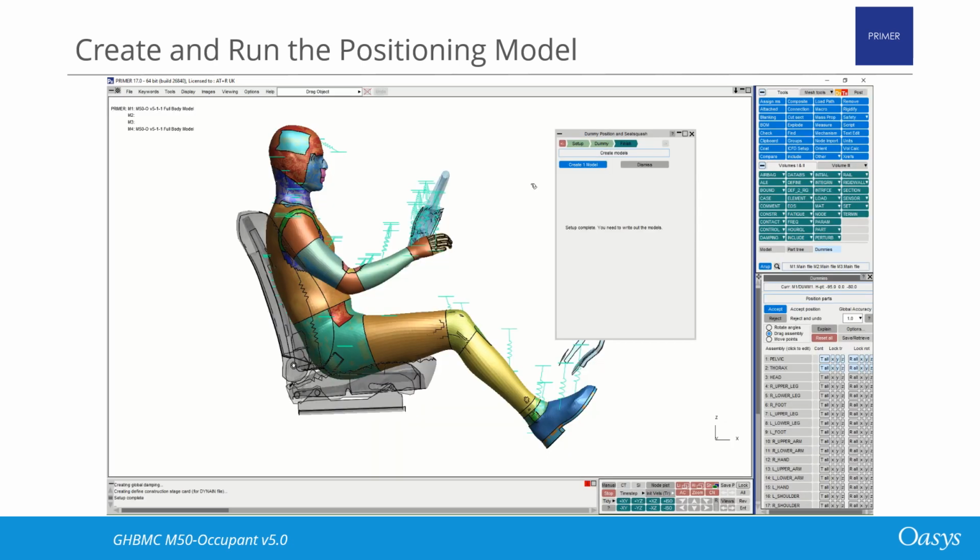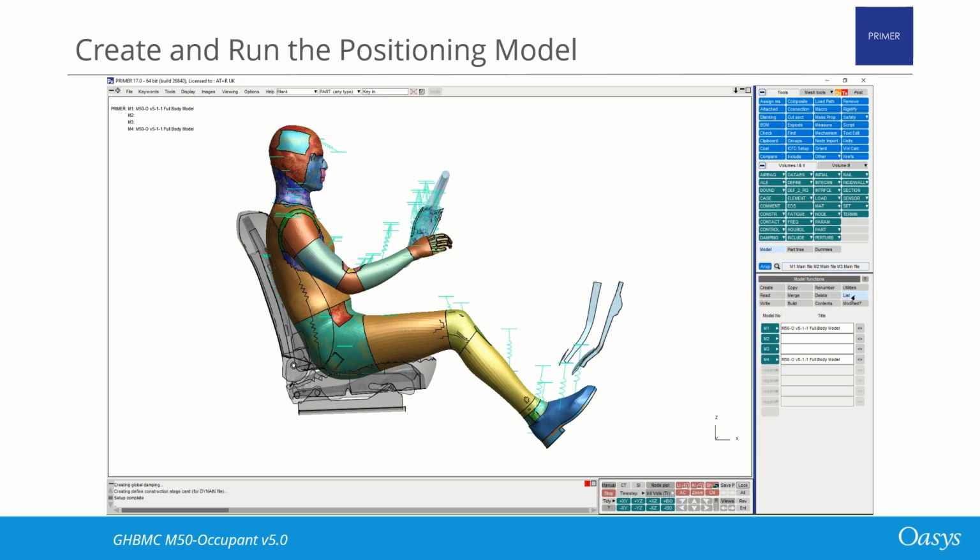So once complete, you can see that Primer has created a new model. The original model has not been modified. You can see the cables that have been created to pull the dummy into position. So here you can see the new model that's been created within Primer. You can now write this model out and run it in LS-DYNA. Now, you should not include the dummy tree include file in the LS-DYNA analysis. This is encrypted and LS-DYNA will not recognize the information included.